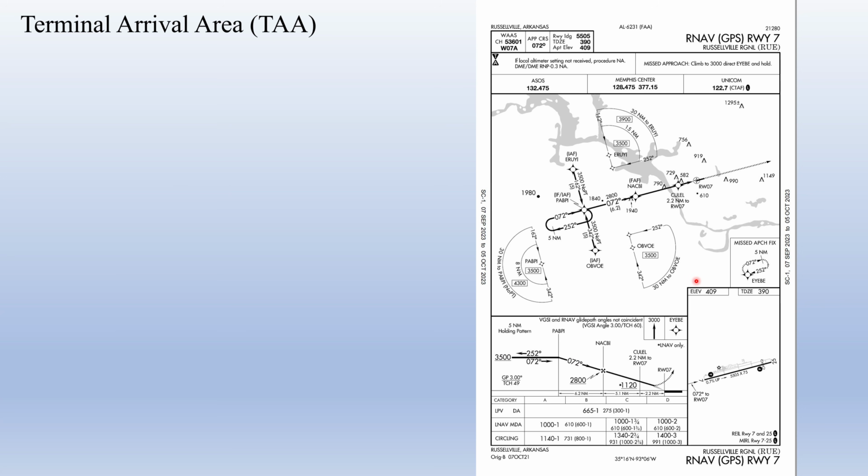So that's how that would work if we're approaching from the southwest. The same sort of thing is true if we're approaching from the southeast and we've been cleared direct to AVO. We'll assume we're up at 6,000. We'll assume we get to 30 nautical miles out and they clear us for the approach. Then we can go ahead and descend from 6,000 down to 3,500 feet because it is a procedure altitude.